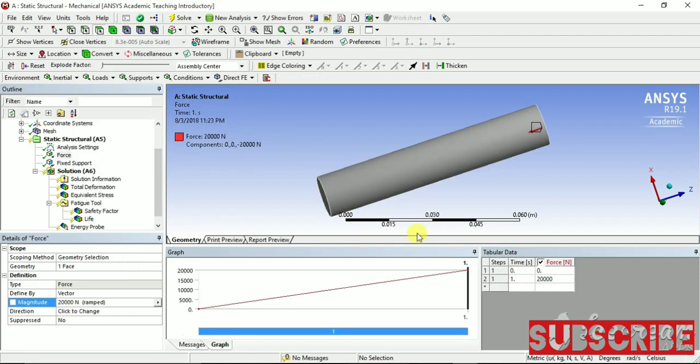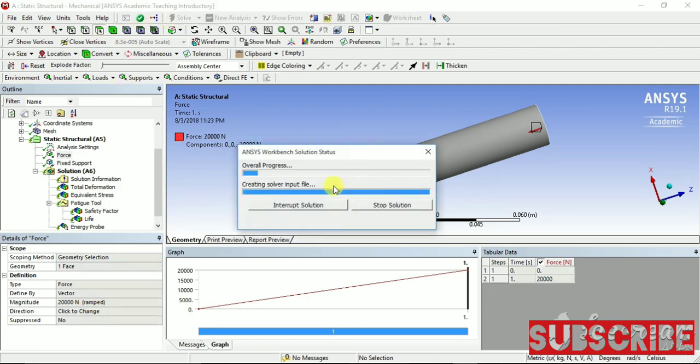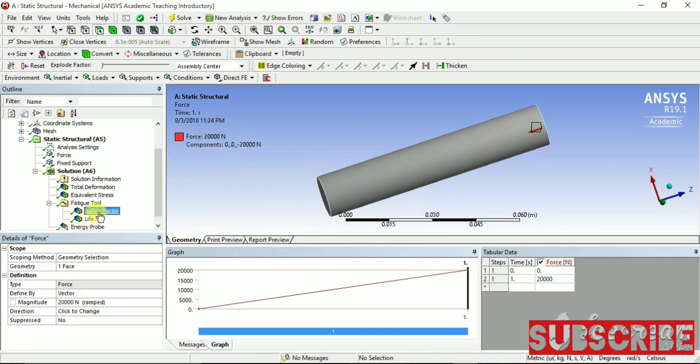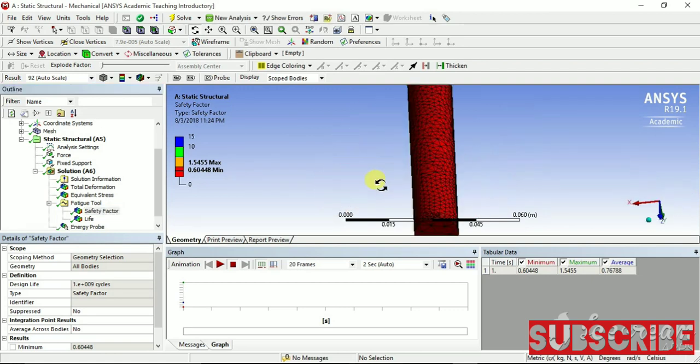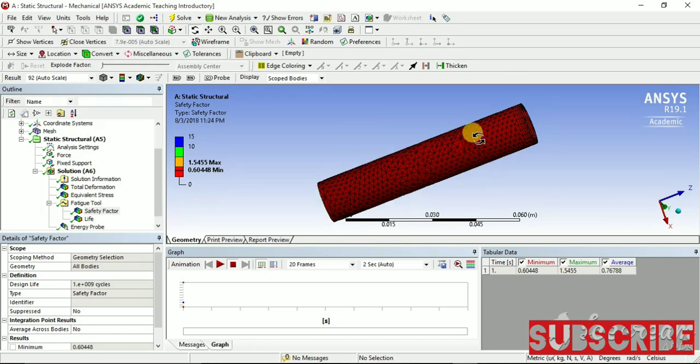Now for the same specimen, if I change the magnitude to 20 kN and solve it, I will get another result. The factor of safety here drops to a minimum of 0.6. That means a particular section of that specimen will fail because of the force applied to it. So this is not a good design for that particular amount of force. In this way we can check different values for different bodies. This was just an example to show you how we can work on this software.